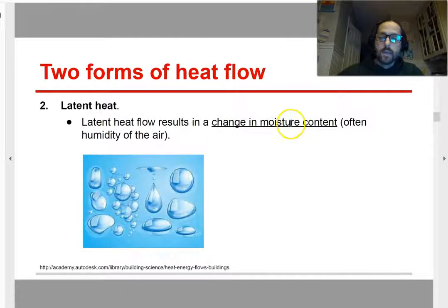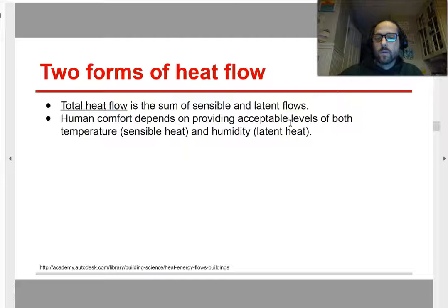But the kind of important thing that we haven't gone over a whole lot but was mentioned is enthalpy. So the total heat flow, or the total heat in air, is based on the sensible and latent heat. If you remember on a psychrometric chart, enthalpy was next to dew point on the left-hand side. That tells you the heat in the air, both in terms of sensible, so the dry bulb temperature, but also the latent heat and the moisture in the air.